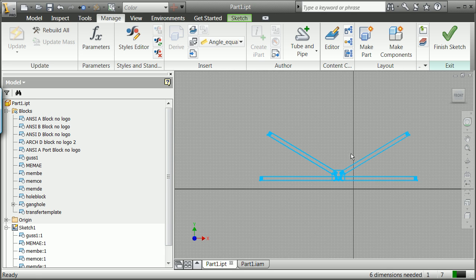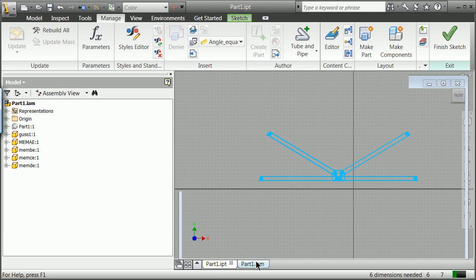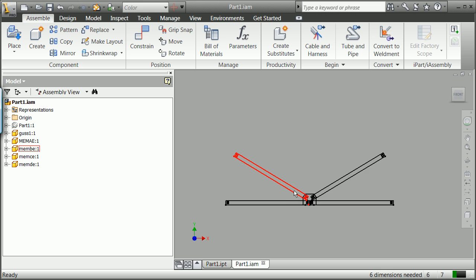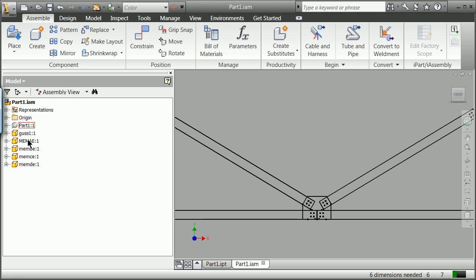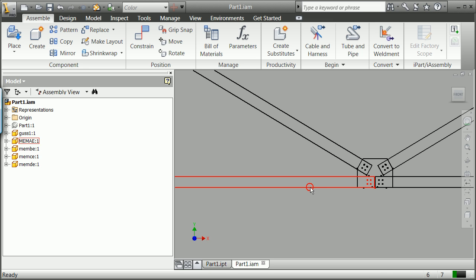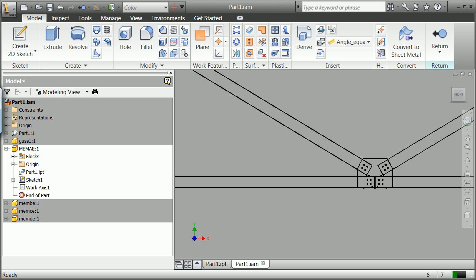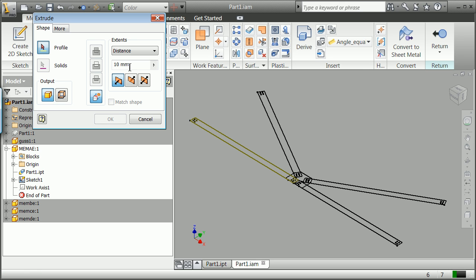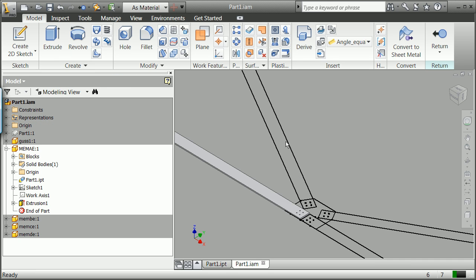It has not done it because it did not. I need to hit apply, and you're right here. I guess it did do it. You hit the double click in here, and now you have in this assembly parts that are made. Now you can go about, and if you double click in any particular part, you can go there and hit F6, and in that part now, when you double click in it, you have the ability to extrude. I'll just do this 25 millimeters coming out. Profile here, click on that, coming out, hit OK, you're out of that one.